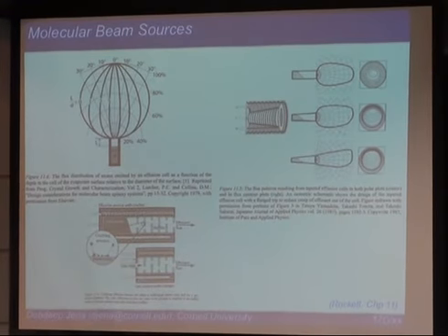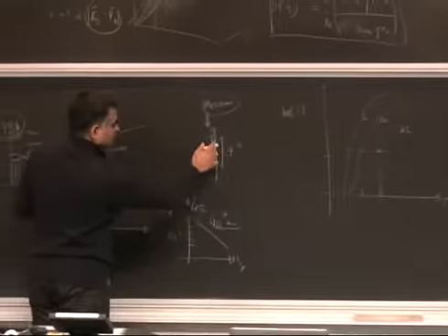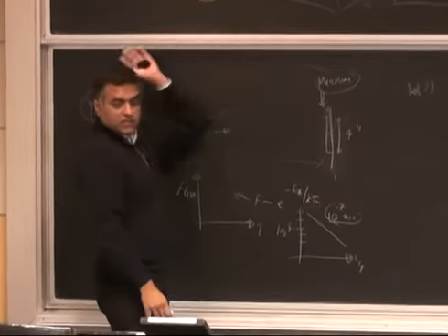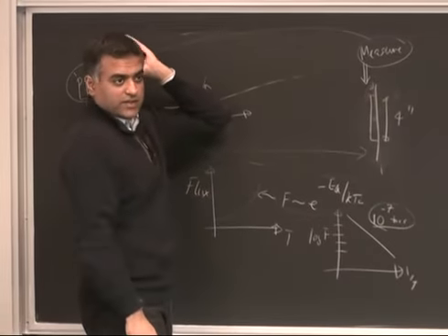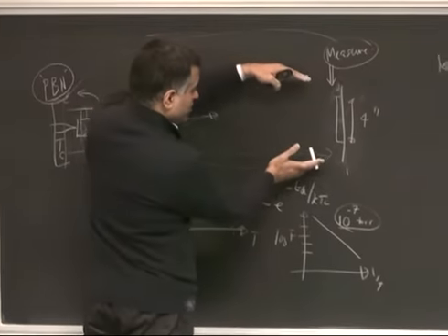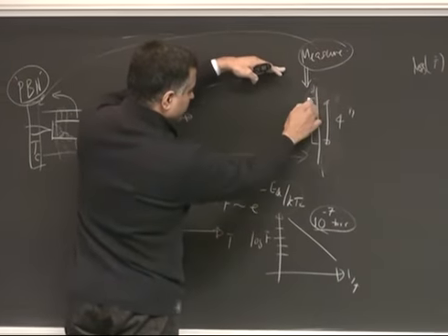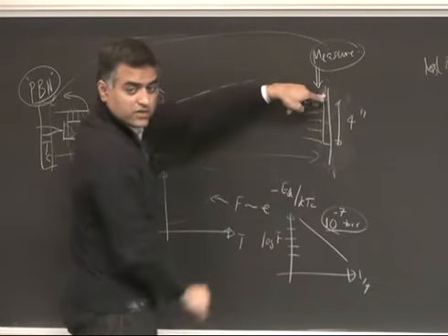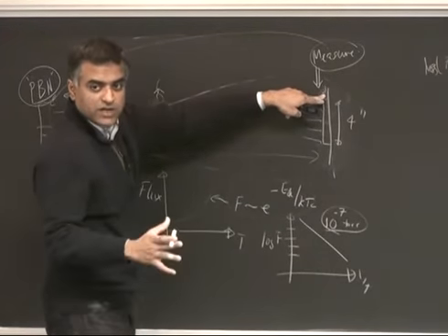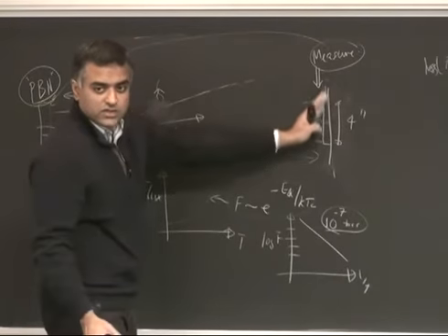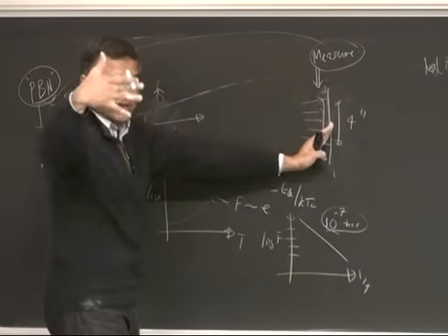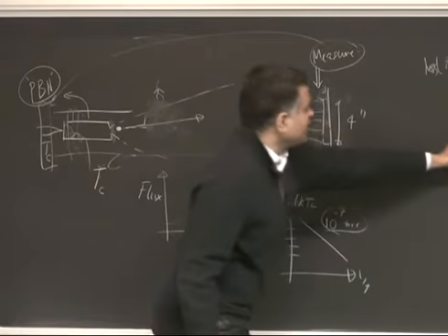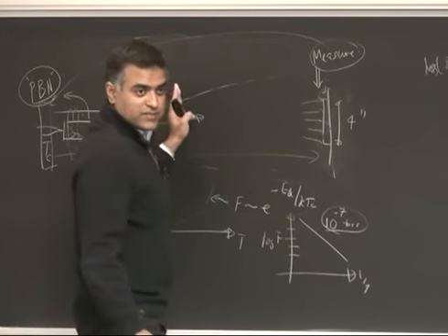Right? And you will have gallium atoms come out, let's say, right? I think it's very clear that you only want gallium atoms to go here. I mean, there's no need for depositing all this out. It's a waste of material, right? So you can, but at the same time, you want them to be very uniform. The flux reaching here should be equal to the flux reaching there. I think you see there's a trade-off, right? If you let it go in all directions, you are assured that it will be reasonably uniform here because it's like far away in some sense, right? If you take it very far, but then you're wasting a lot of material, right?